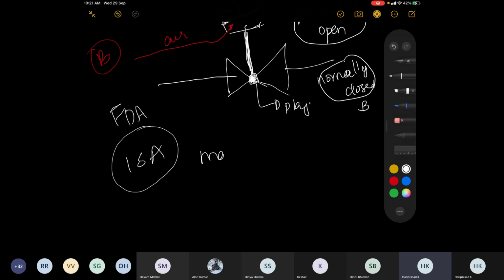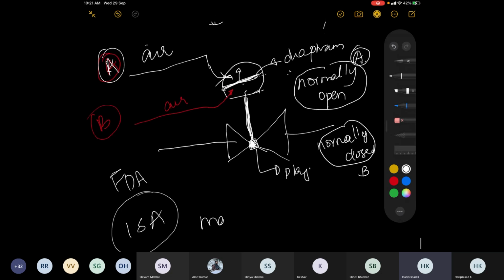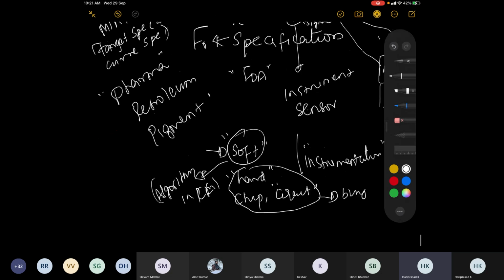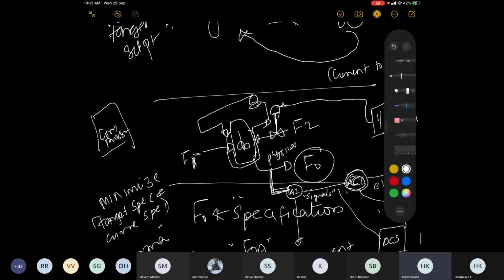Let's say one of you is given the job to design a controller. You would start with identifying what the analyzer is, what the transmitter is, then you will also take a look at what I to P range you want, then you come to the control valve. You have to buy all this from the market.